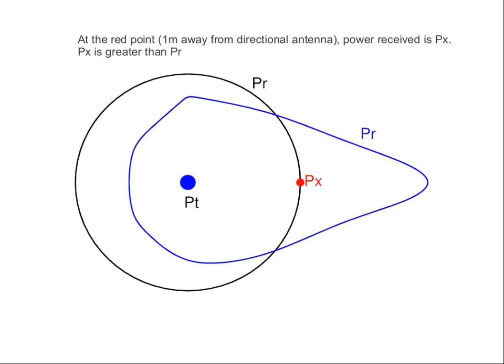And the notation we use with antenna gains is that my directional antenna is 2 times stronger than using an ideal isotropic antenna. Or in decibels, 3 dB. And to indicate this 3 dB is relative to an isotropic antenna, we add an I, lowercase i here, and we get dBi.